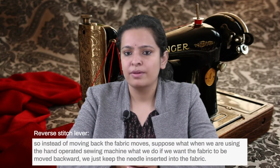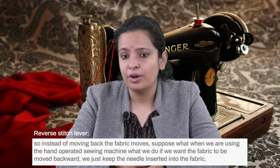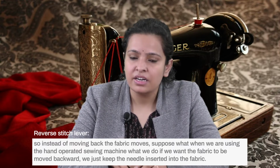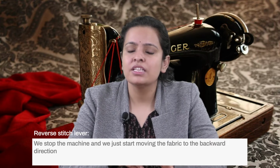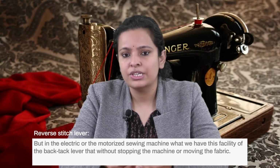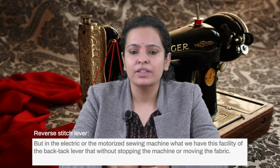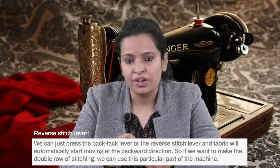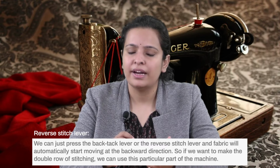As soon as we press the lever down, the direction of the fabric movement changes. If we want to change the movement of the fabric from forward to backward, we press this back tack lever or the reverse stitch lever. When we are using the hand operated sewing machine and want the fabric to move backward, we keep the needle inserted into the fabric, stop the machine, and start moving the fabric in the backward direction. But in the electric or motorized sewing machine, we have this facility of the back tack lever, so without stopping the machine or moving the fabric, we can just press the lever and the fabric will automatically start moving in the backward direction.